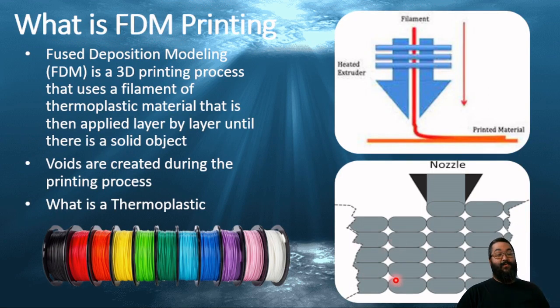So in this picture, it doesn't really do justice to how it is. With my printer, whenever it creates this G-code from the slicer, in PrusaSlicer you can change this. It allows you to rotate each layer by 90 degrees. So you can change that so all these aren't one direction within the print. One layer will be in that direction, and then the next layer will be 90 degrees, and they keep rotating perpendicular to each other, which is how the default is. So this picture is more to demonstrate what the voids are and how they're formed within the part.